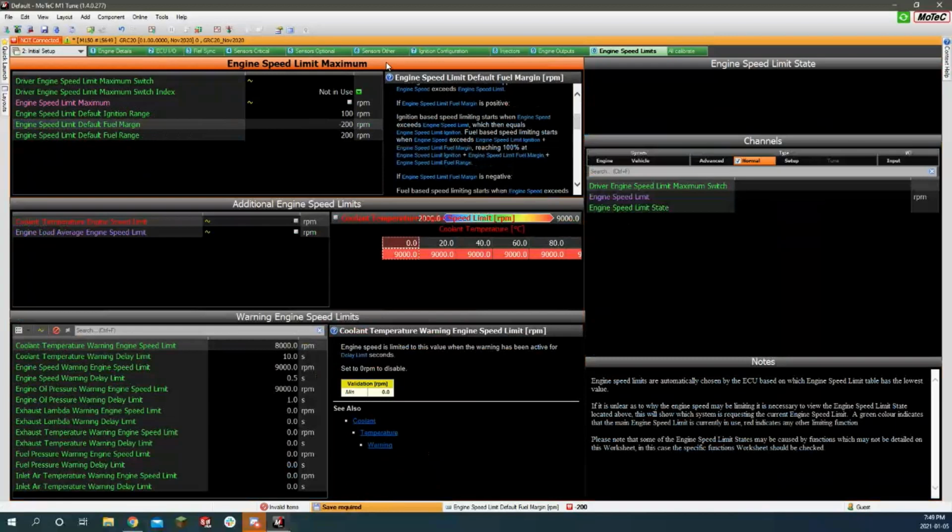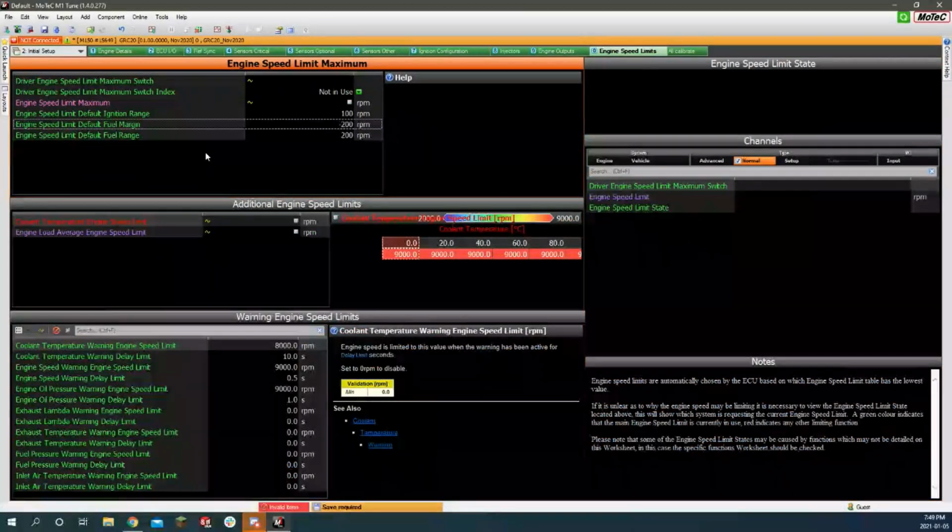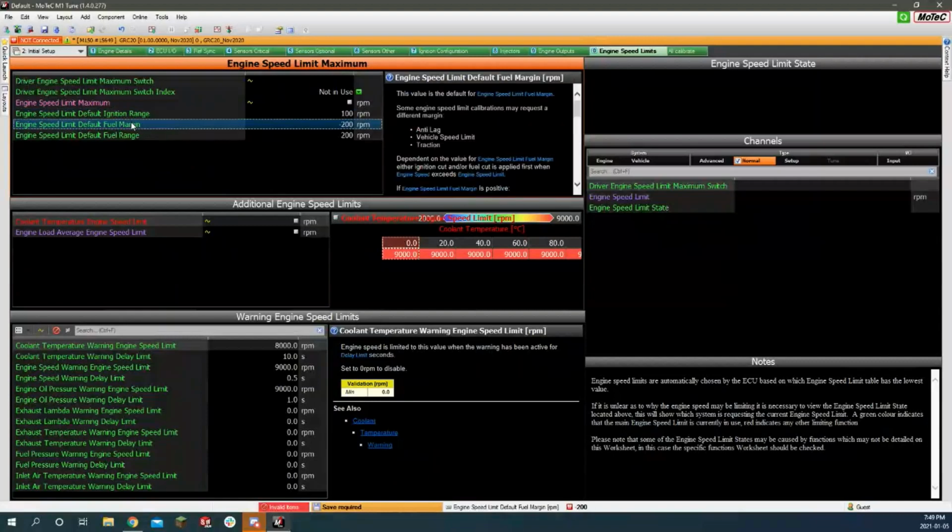That's something the guys at High Performance Academy on YouTube talked about. He's talked about that in a lot of different videos. They had one scenario where they switched engines, and they were using a Motec, and he forgot to change it from an ignition cut based rev limit to a fuel cut based rev limit, which is what we have, where it does the fuel cut first. They ended up pretty badly damaging their engine just because he missed that parameter. So something super important.